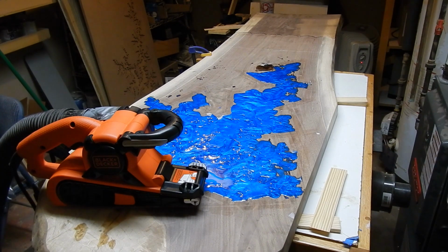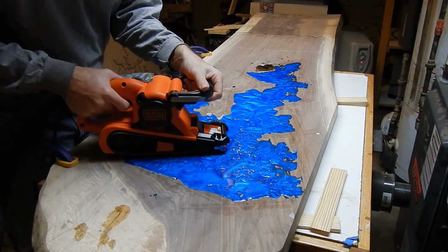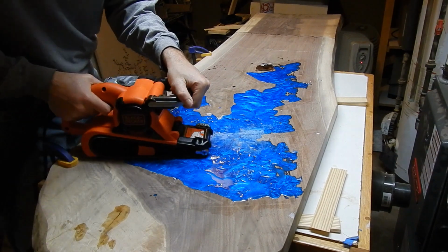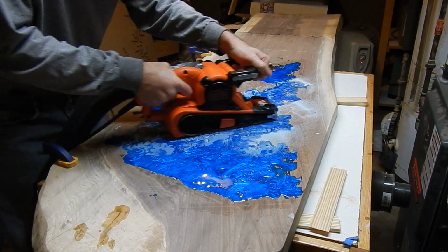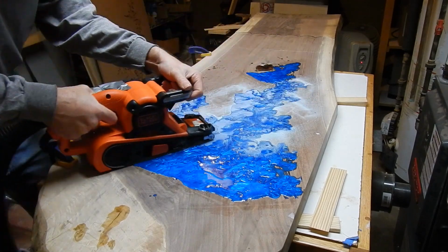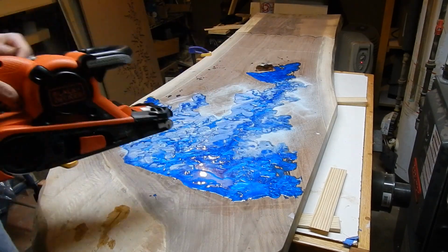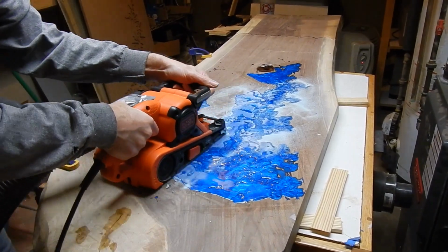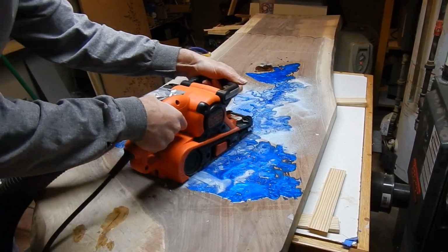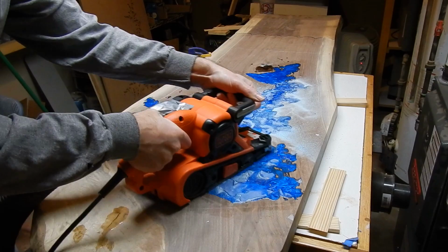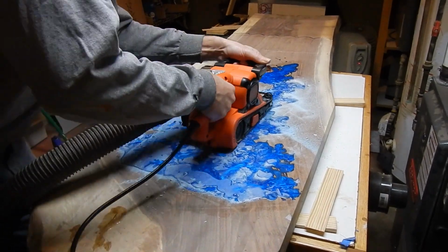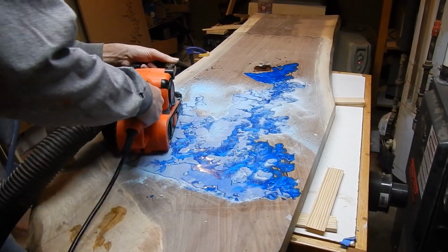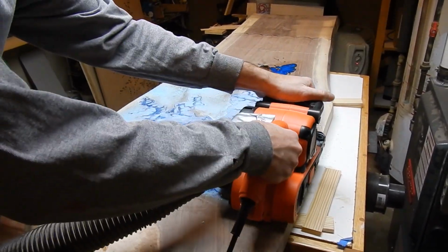While I really liked the blue epoxy and the look that it gave in this 3D state, it was time to sand it down. I went out and bought a new belt sander. It worked out pretty well. I started with 80 grit, but it wasn't taking off enough, and so I moved down to 60 grit. That worked great. I went from 60 grit, got most of it off, then went to 80 grit and went up to 120 and took it down until I was happy with a nice smooth surface.